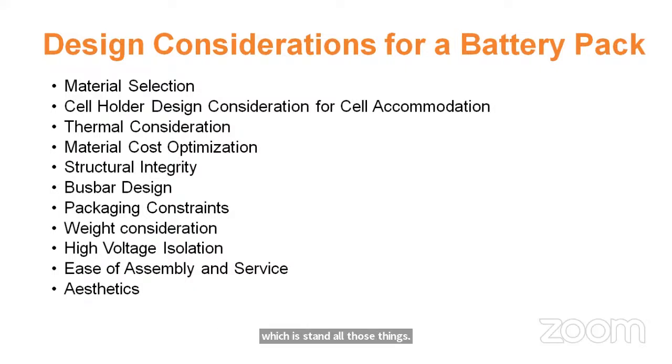Bus bar design. This is a very important thing. Our bus bar should be designed in such a way that, bus bar design means the thickness and the width of the bus bar, meaning the cross section, should be sufficient to carry the current, and it should not get heated up. For each particular current requirement there are some thumb rules: this much current is there, then there are some basic calculations, this much current has to flow through the bus bar, then this much thickness and this much cross section should be there.